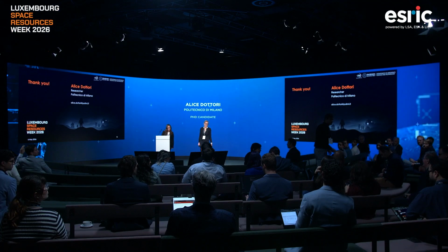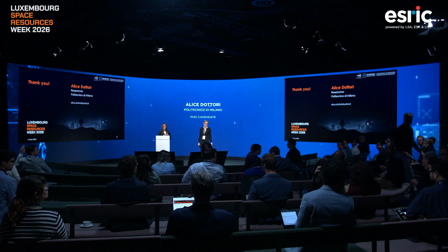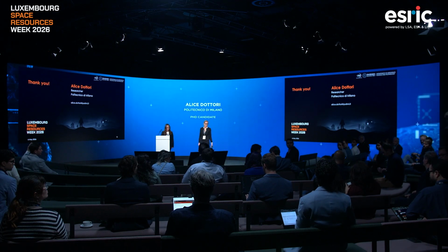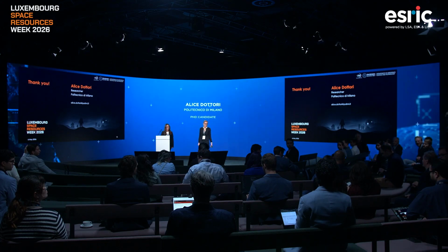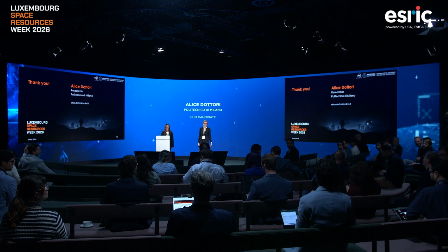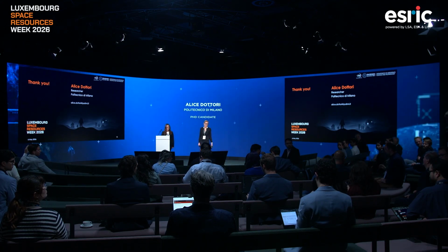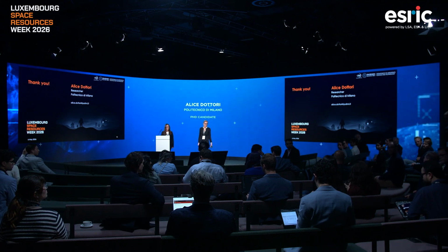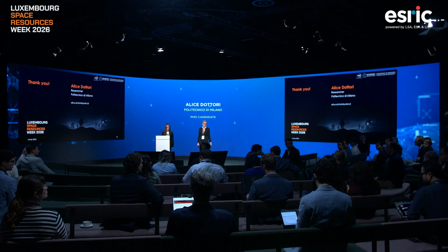So we just bring it once. I wonder if there's enough methane on the moon to make it worth it. I was just wondering if you'd calculated that. Well, you don't need to make the methane on the moon to reach orbit. This process recycles the methane. And if we do find a carbon source, then we will make the methane. But since the propellant mass is 75% oxygen in the first place, you can bring methane from Earth and still have regenerators with just the oxygen.